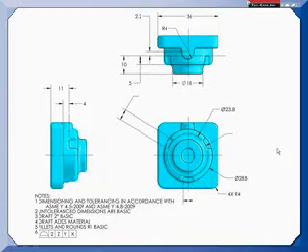Before we get into walking through that, I would like to mention, because some people are probably saying well, we deal with castings and we like processing datums. When I think about a casting, and here's the casting for that block, it's really a separate part. Its function is to machine clean. And so when I look at a casting, I ask the question, what features in the manufacturing process are going to constrain the degrees of freedom to make sure that this thing will machine clean?